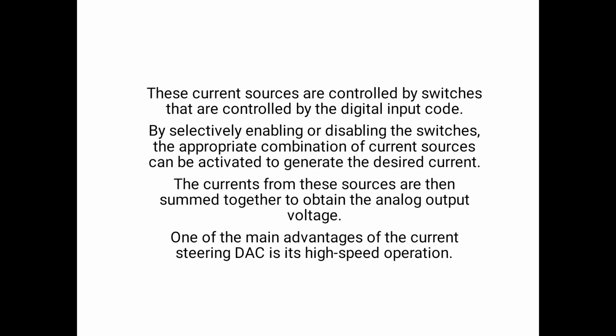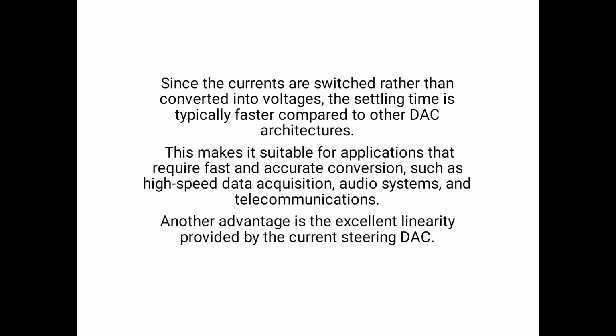One of the main advantages of the current steering digital to analog converter is its high speed operation. Since the currents are switched rather than converted into voltages, the settling time is typically faster compared to other digital to analog converter architectures.